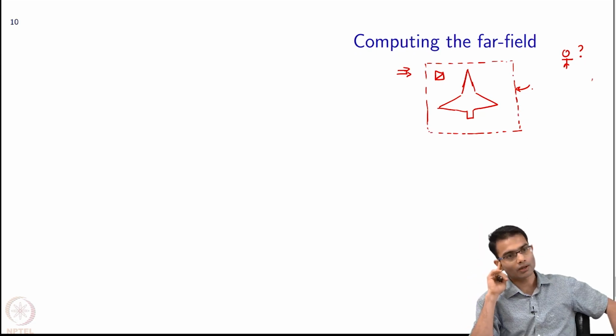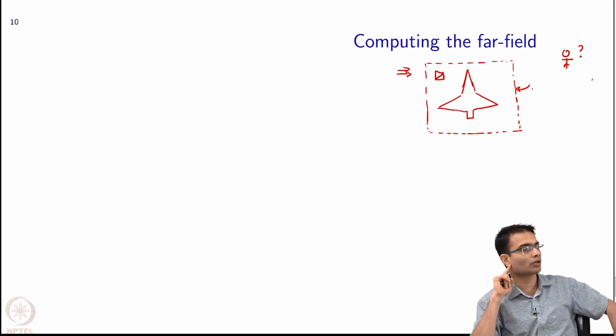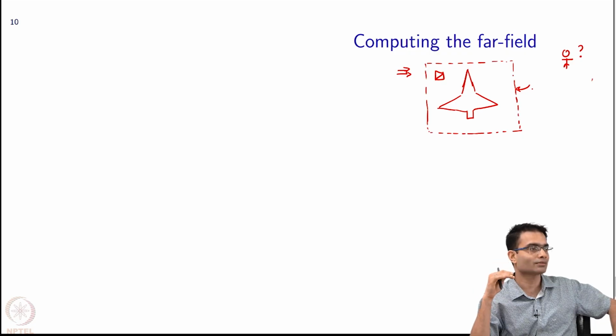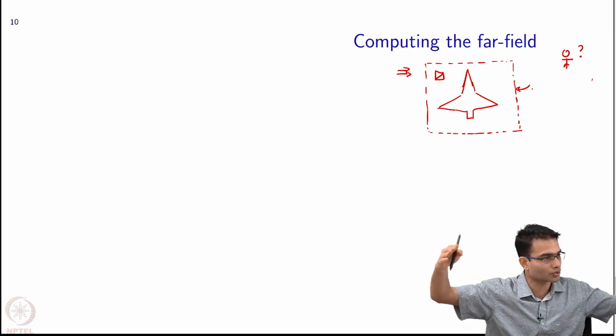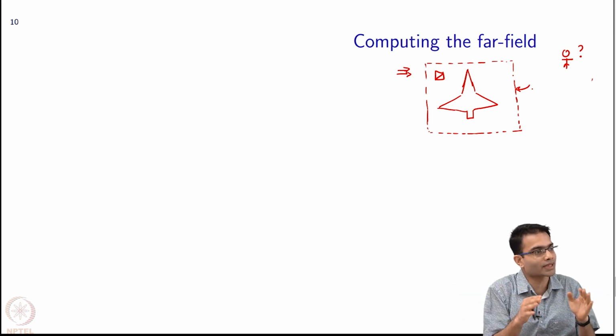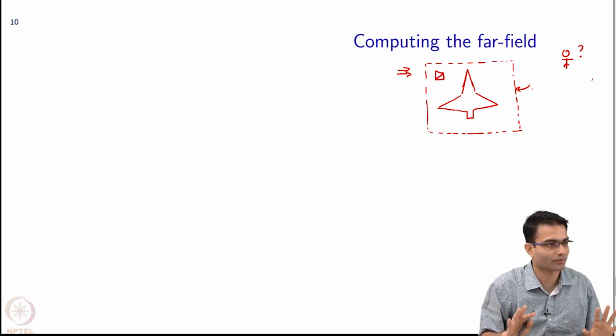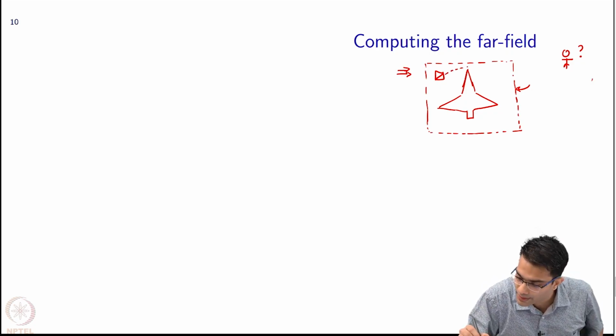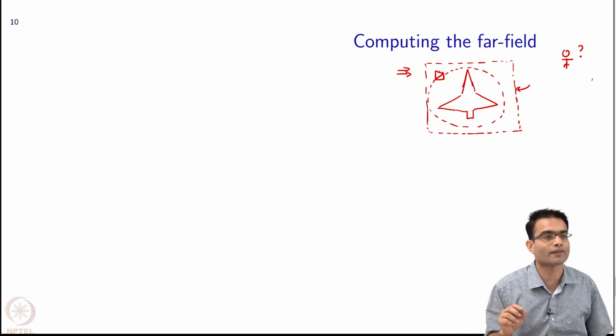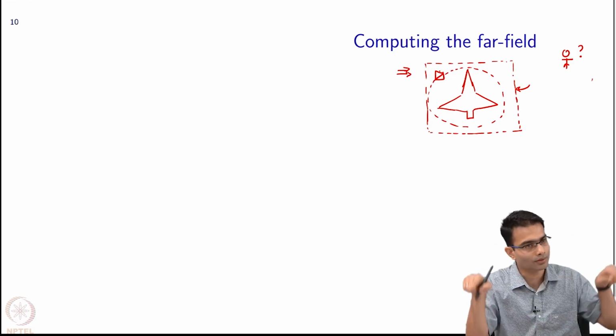Now we have had a discussion on boundary conditions, and we have seen that, for example, the radiation boundary condition we have used is inexact. So the error of the boundary condition grows as I get closer and closer to the boundary. As I move further inside, it gets better. I am just giving you information, we have not actually calculated it. So what would be better is if in your mesh itself you had a nice set of edges like this, which defined a boundary.